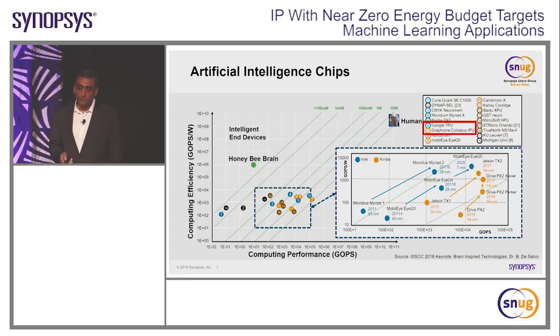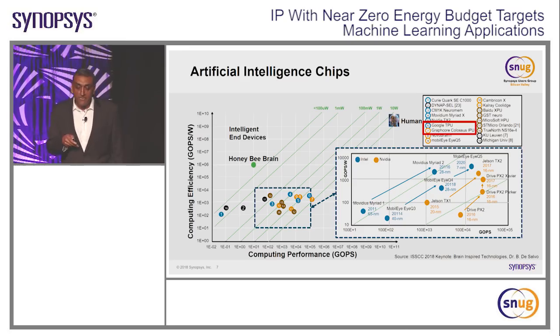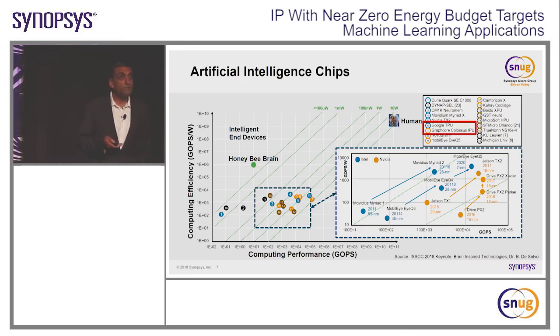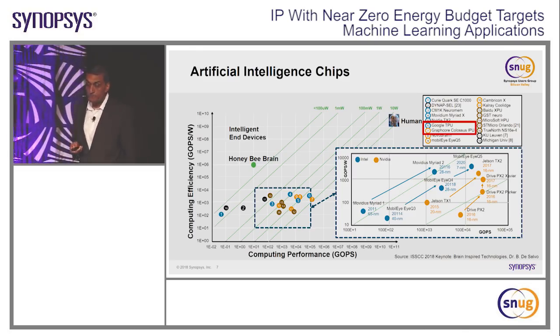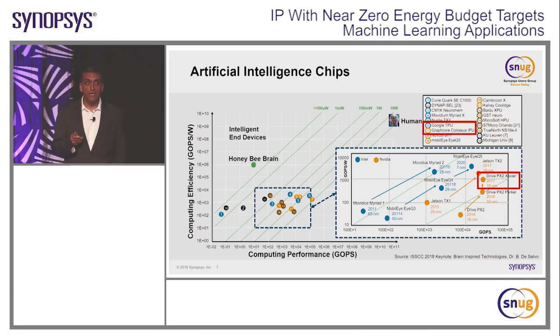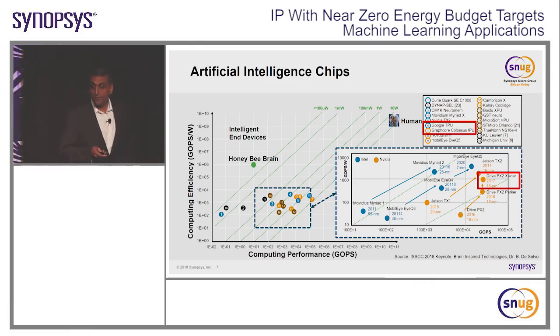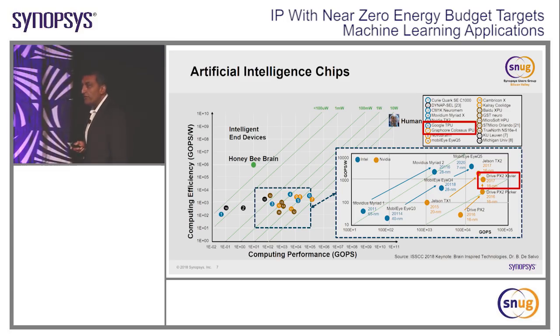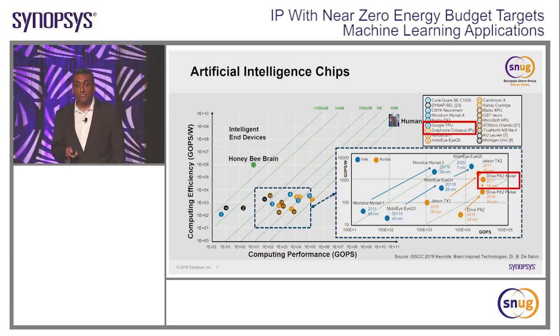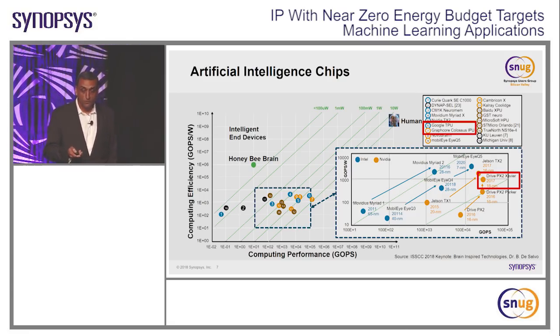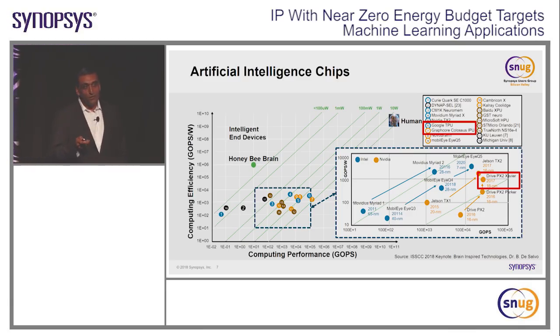And just to close out, inspecting the latest set of designs and making the comparisons between Intel and NVIDIA, I'm going to show an example of NVIDIA's Xavier chip. This is 9 billion transistors. It's an 8-core CPU. It uses 512 Volta GPUs. It has a new deep learning accelerator, which can give you 30 trillion operations per second. It consumes 30 watts. Still, it's not close to the target of the brain, which gives me a lot of comfort, actually.